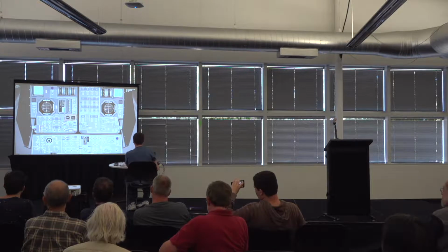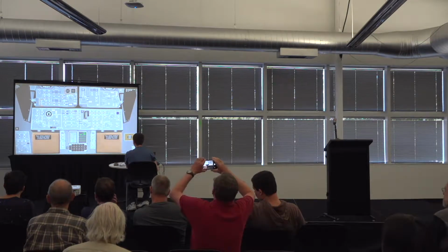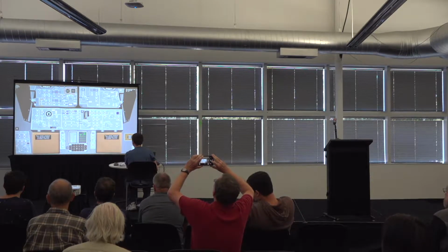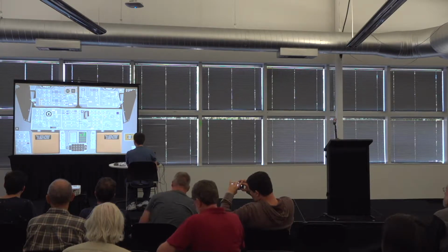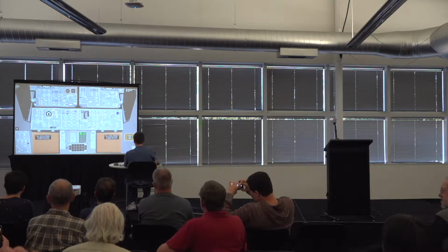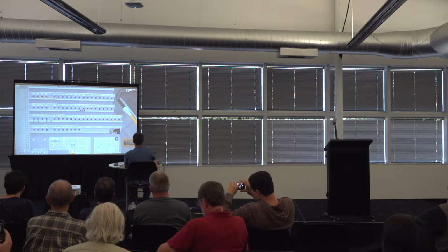Okay, so the first thing that I have to do is start program 63. Program 63 is the landing program. It is specifically the braking phase, so this will take us out of orbit. So I'm going to do verb 37, enter, 63, enter. Verb 37 is start program. While that's thinking, I'm going to look over to the left and push in the landing radar circuit breaker to turn on my landing radar.